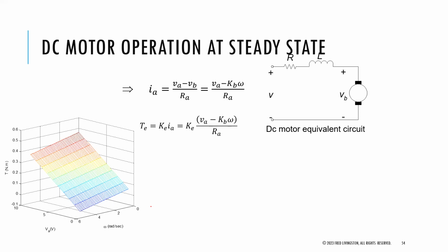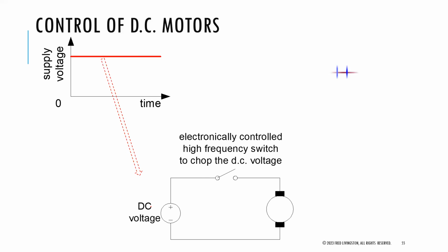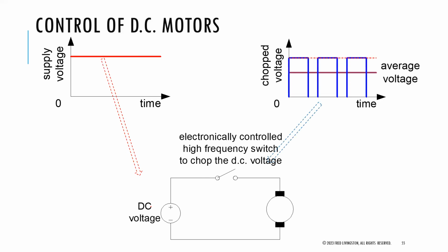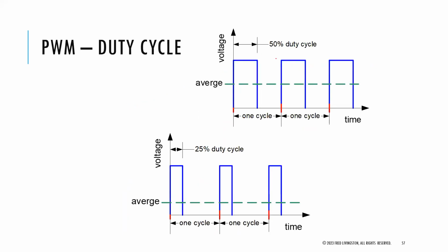And then eventually I want to control the system. In that case, we had a DC motor and a conveyor belt. We wanted to move at slow, fast, and medium speeds. So we gave it a pulsing signal, a duty cycle, to control that in one of the labs. By pulsing it, the average voltage, which is represented in red, is equivalent to the amount of time high or low in those pulsing cycles. Giving a small pulse, we had a lower average voltage, and given a larger pulse, we had a higher average voltage.